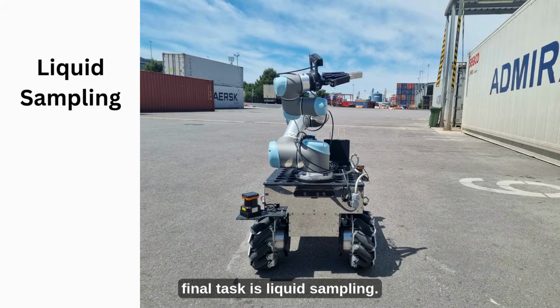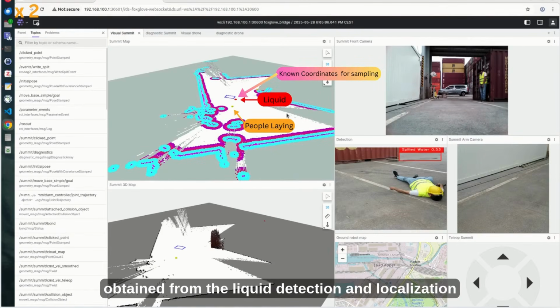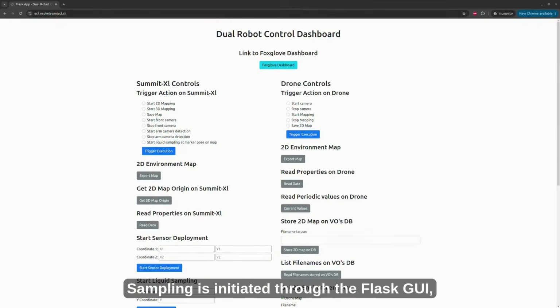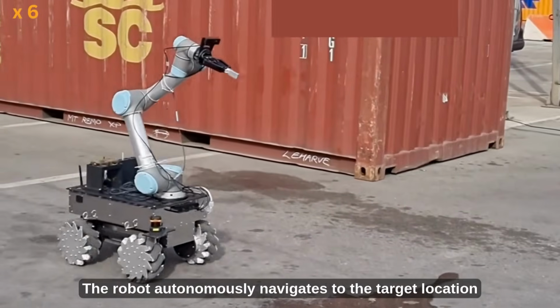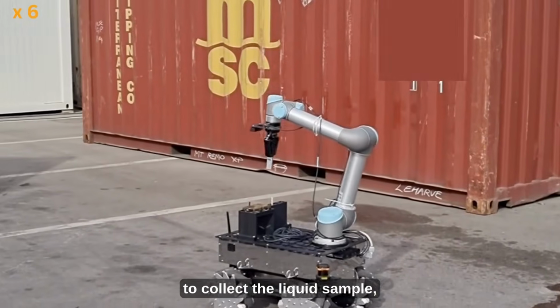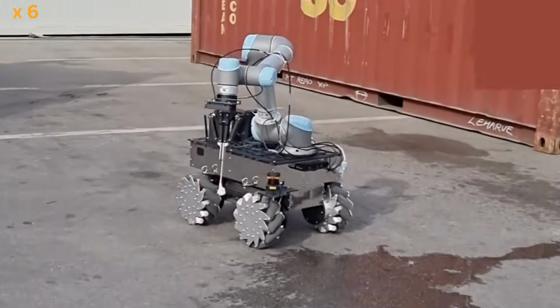The final task is liquid sampling. The coordinates for sampling are obtained from the liquid detection and localization process. Sampling is initiated through the Flask GUI, which sends a command to the robot to start the mission. The robot autonomously navigates to the target location and uses a cotton swab attached to its gripper to collect the liquid sample, placing it back into the pallet afterward.